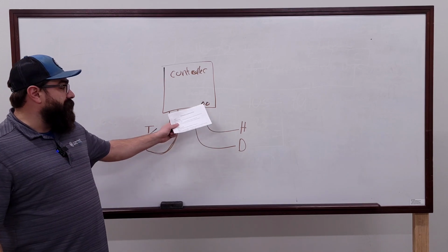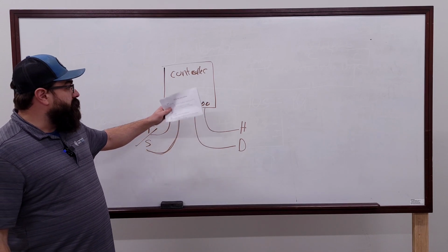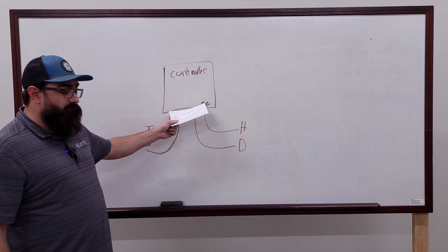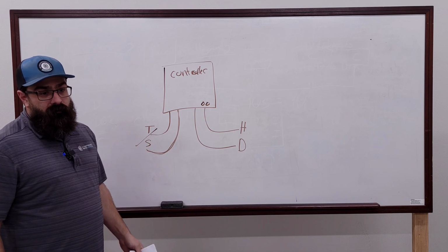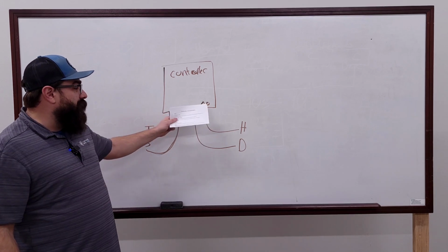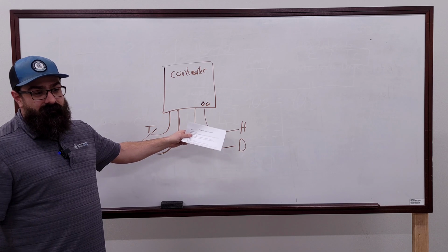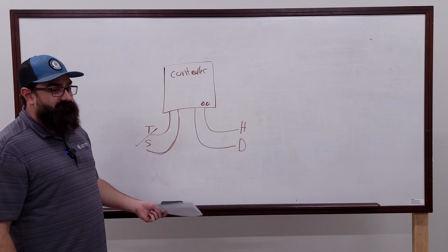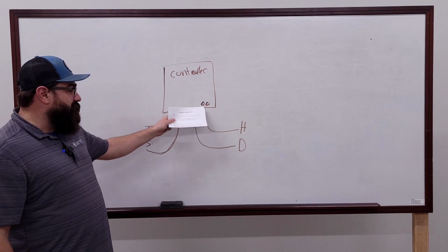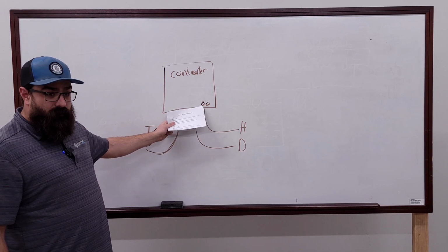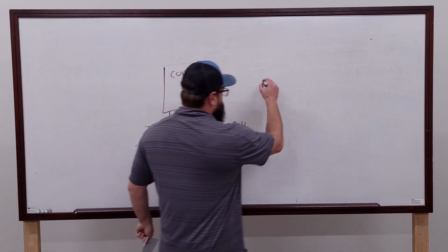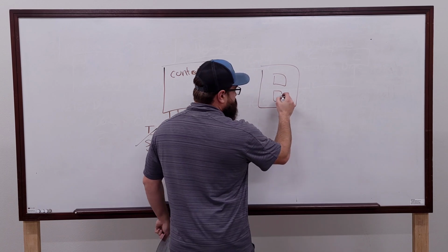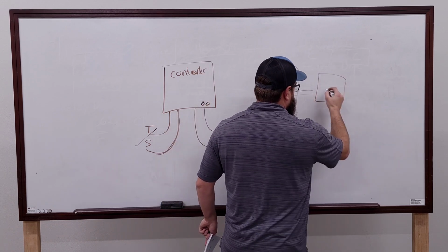So if you're not getting a value here, either this controller is not calling for it, you've got the wrong output, or the output's bad. Or it could be miswired and it could be grounding that output out and you're not reading an output, even though it has one. That happened to me last Friday night. I would come to the controller, get an output. This controller then went over to another panel, which had some EPs in them. And then those EPs sent pneumatic out to a valve actuator.